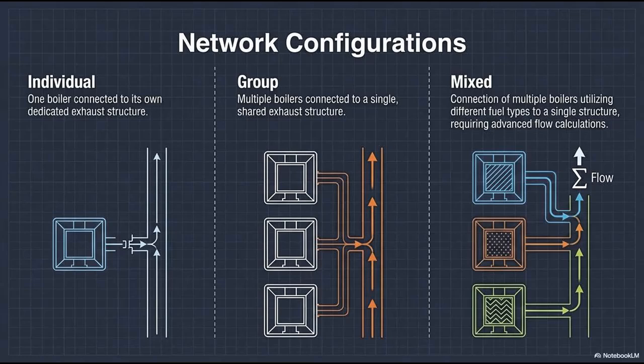Okay. So we've established how the machine inhales and how our modern renovations are starving it of air. Now we need to look at how it exhales. The exhaust side. Right. If the boiler actually manages to get enough air to burn, where does that exhaust go? Because I was genuinely shocked to learn that a badly constructed chimney can take a state-of-the-art, hyper-efficient boiler and utterly destroy its performance. Oh, entirely? Like dropping its efficiency from 95% down to a dismal 60%.